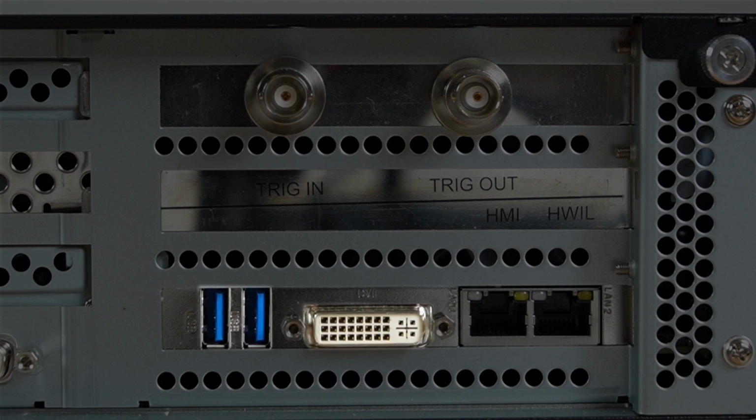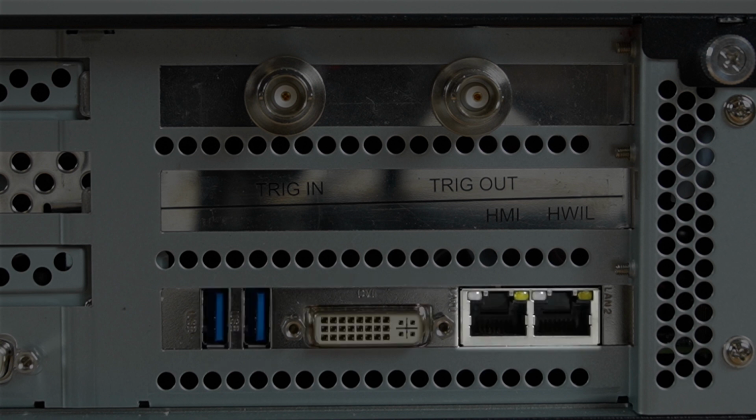On the bottom, you've got 2 USB 3.0 connectors and 1 VGA video output. In addition to this, there are 2 RJ45 Ethernet connectors. These 2 plugs have very specific purposes. The first one on the left, with the HMI sticker, is used to connect your Constellator to the computer that hosts the GUI. You can either connect your HMI computer directly to this interface or simply plug it on a shared Ethernet network. The other Ethernet interface is reserved for the hardware-in-the-loop feature. Hardware-in-the-loop is a specific feature that allows you to inject a receiver trajectory to simulate in real time.